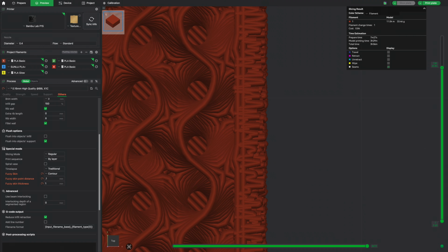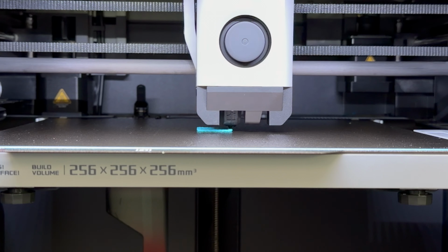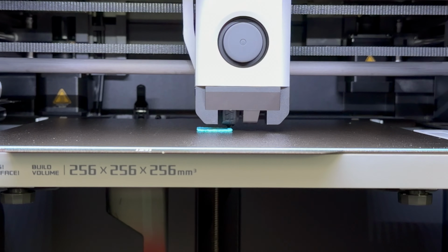The print head was colliding with the print itself. There was a little clue to this in the slicer. When looking at the problem cubes, you could actually see the path intersecting with the other parts of the object. Testing a single cube showed this in action.